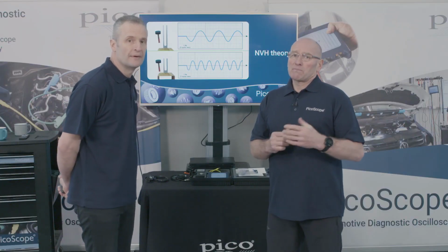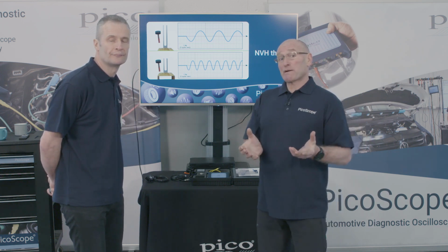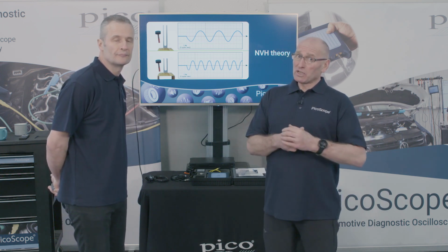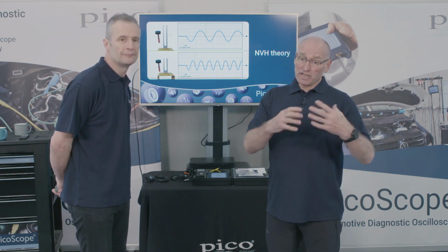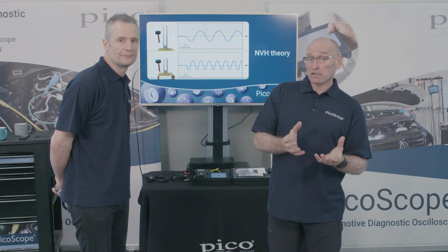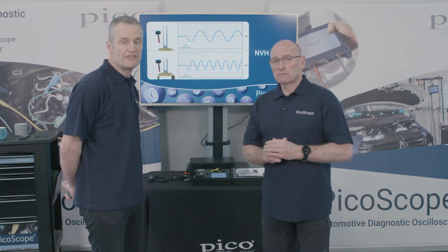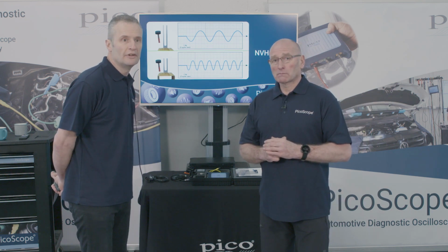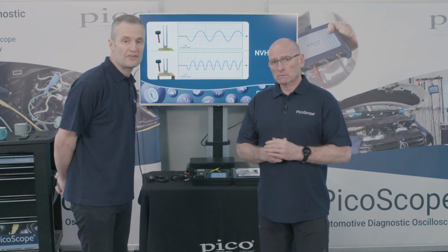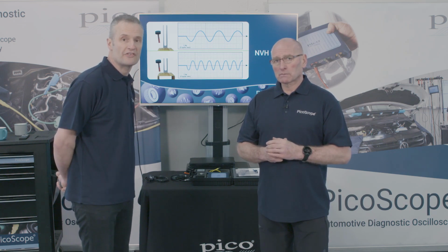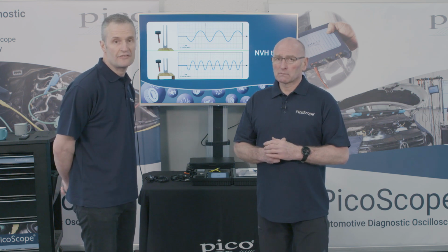So what we've done here in effect is we've taken a vehicle, we've put some sports suspension on it, we've lowered the suspension, and we've done exactly what that animation has just shown us. We've changed the natural frequencies at which that vehicle now will demonstrate vibration. Yeah. The rigidity, if you like, has changed. So with the tuning fork example, the way in which that vibrates, it will now be a higher frequency. It's a stiffer, more rigid fork. Relay that to the chassis.